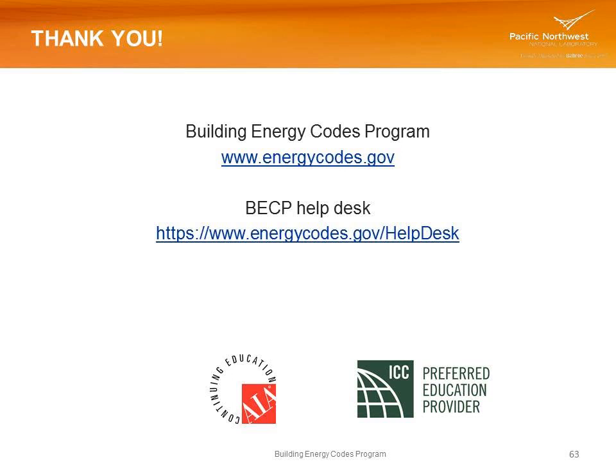Considering occupant comfort, which system is more effective, air distribution or radiant systems? Which is more energy efficient? You know, there's probably a debate on that. Most of our systems are typically air distribution systems. There are some people who would advocate for radiant systems, and if they're properly installed, a radiant system can improve comfort. Part of the advantage of a radiant system is that I can be comfortable, say, in the heating mode when the space temperature is as low as 65 degrees, because I'm receiving radiant heat directly on my body.